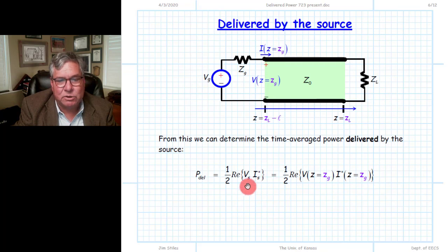So we know this value is going to be positive when we, again, define positive current as moving down the transmission line. So by KVL and KCL, we can see the voltage here at the beginning of the line is going to be equal to V sub S, and I didn't define that on the circuit. I should have. V sub S would be the voltage here at the output of the source, and therefore the input to this transmission line.